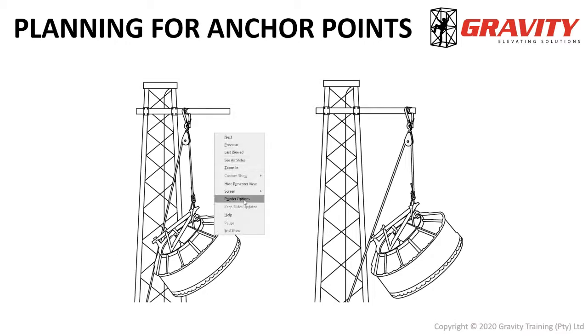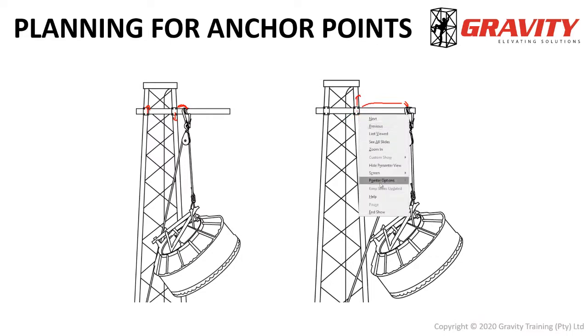If you look on the left-hand side, due to the distance there being quite small, the amount of force you're putting on this bracket and that bracket is relatively small. Whereas this creates quite a large moment and will put quite a significant force, sorry, wrong direction, quite a large force on these brackets.